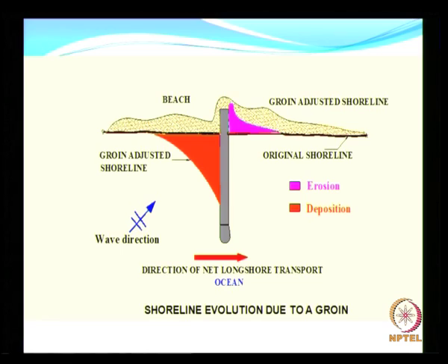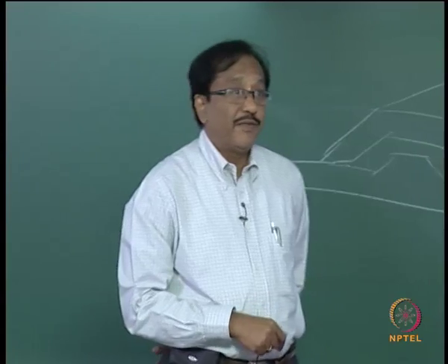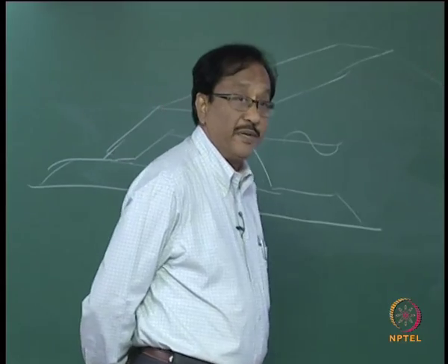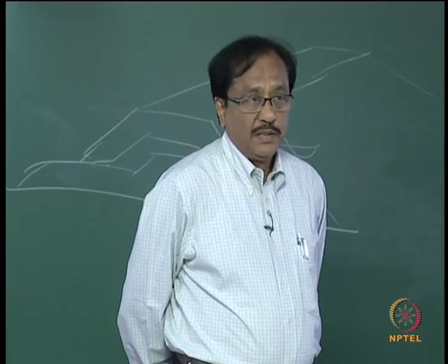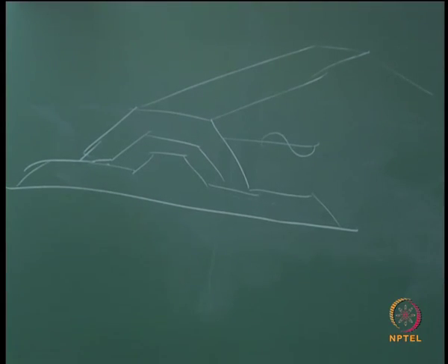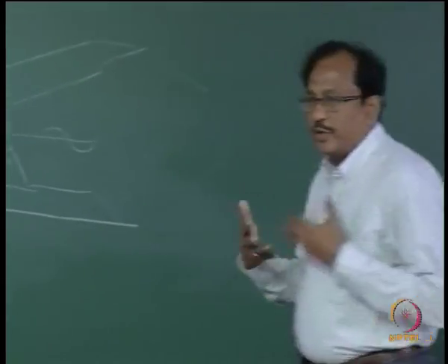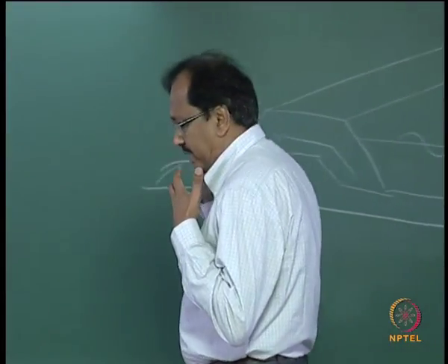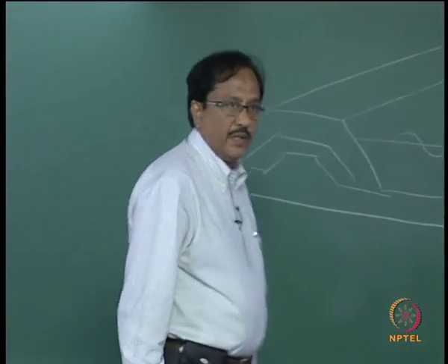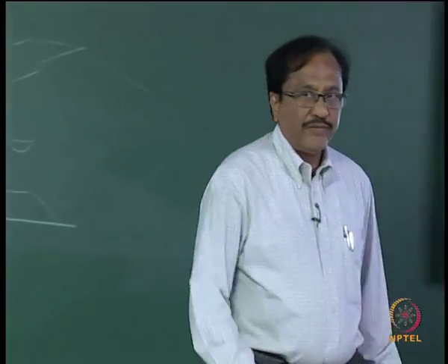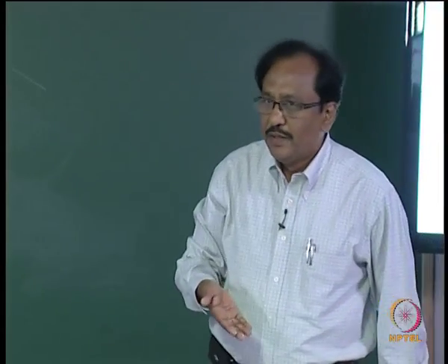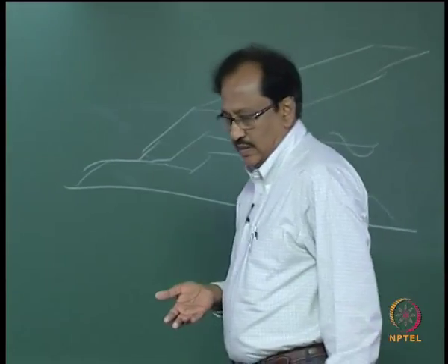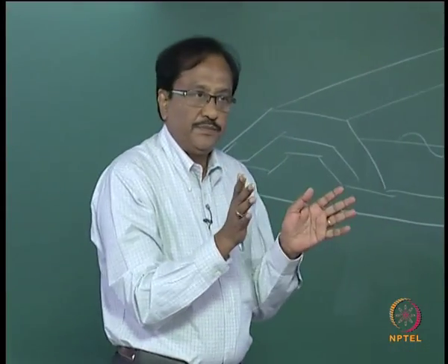Which is the one which is really governing the direction of littoral currents or littoral sediment transport, the sediment transport? So, when you are dealing with the sediment transport, it is not only the magnitude which matters, it is also the direction which is very important. Of course, the direction is going to be governed by your basic Snell's law, it comes only from your refraction. So, this point is very clear now.